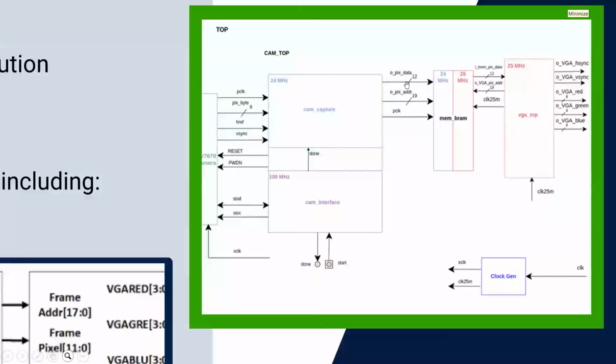So for the reading part and the writing part, you are writing this memory at a 12-bit rate, and you are outputting this 12-bit output to a VGA monitor, an IC which is practically giving you those pixel data on certain conditions and frequencies. So this is the write address which we use to write in our VRAM. And based on my write address, my VGA is going to read that many addresses from that OV7670 using this memory VRAM interface. VGA top is an output module.